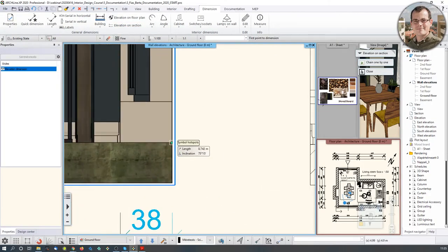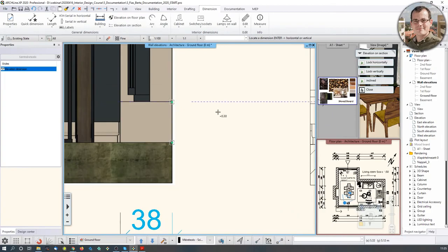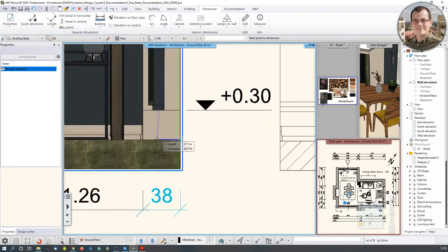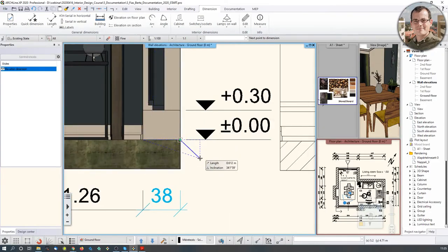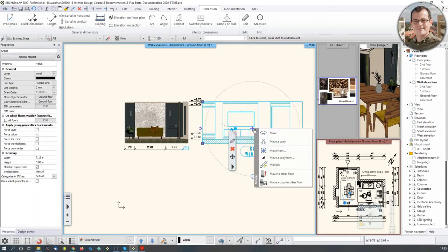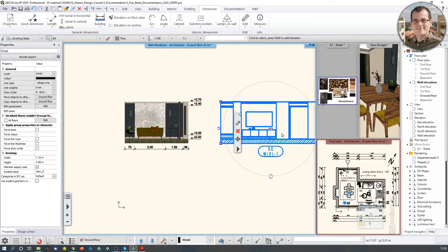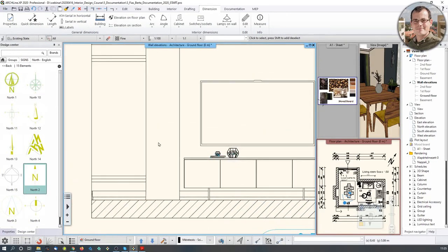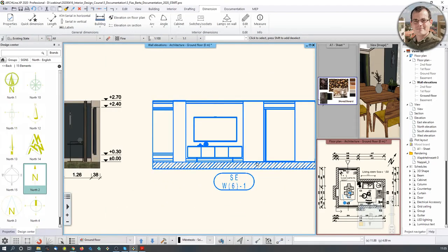So first, again, just follow what is written here. Pick the first point to dimension, and pick the second point and offset the numbers like that, like this, and I forgot about the 0, so I'm just going to hit that as well. So that's how you can do it on an image version. If you want to use it on a drawing version, then it's even easier, because then you have all the numbers or the nodes over here, so you can snap to these points easily.